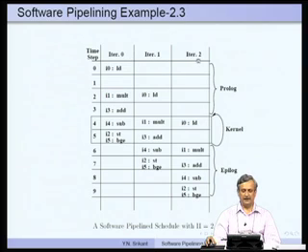So, iteration 0, iteration 1 and iteration 2 as usual have been unrolled. So, we have load, mult, add, sub, store, BGE in this iteration, in this sequence. Then iteration 1 we start I0 here and then go on, then again I0 here and then go on, etcetera. Why are we doing this? Why couldn't we have started I0 here or here and so on? The point is we must have sufficient number of resources to execute the instructions of the second or third iteration in the same cycle. We can't start another load here because load requires 2 cycles to complete and there is only one load store unit. We are assuming that more than one load cannot be issued at the same time by the unit anyway. So, that is the reason why I0 has to start here.